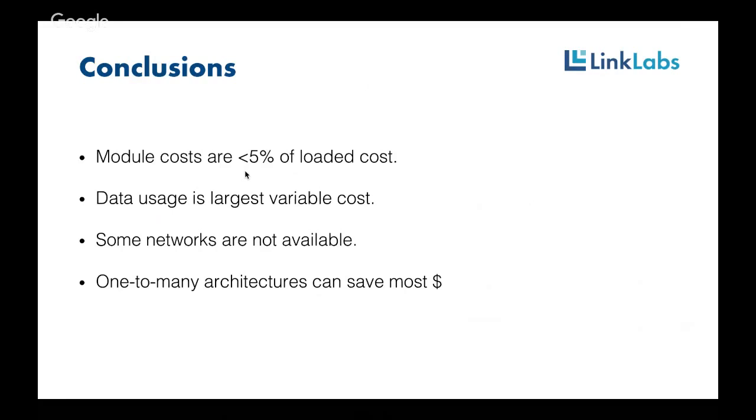Another conclusion here is that data usage is by far the largest variable cost for a lot of these technologies. NB-IoT especially, LTE-M is structured in such a way that it's probably 10 to 100 times more expensive per byte than your smartphone's data plan. So keep that in mind.